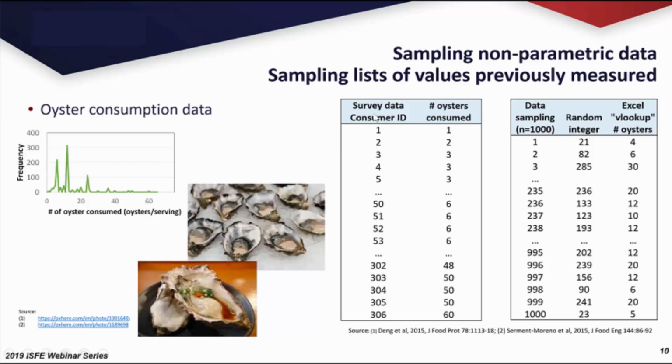Okay, so I'm not going to go through how we built this Excel because it will take an enormous amount of time and it's not so friendly to do it in a webinar. But let's say that I'm doing my calculation here to obtain 180 days of shelf life. They want to have a 5 percentile failure risk. And in that case, this would be the water vapor transmission rate. This would be the permeance value for the situation. And this is the fill weight.